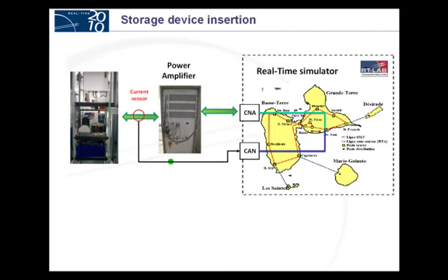Okay, so this is what we have done. We have to test this kind of insertion of storage device. We have done some PHIL application. So we measured here the voltage in Sainte-Anne substation, and we connect our real device through our power amplifier, and we re-inject the current inside the Sainte-Anne substation. So this is another application of PHIL, which I have presented at the beginning.